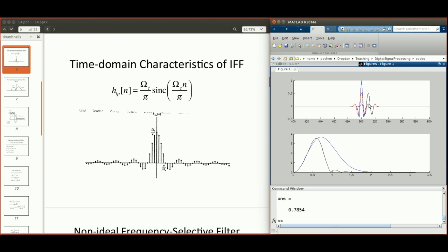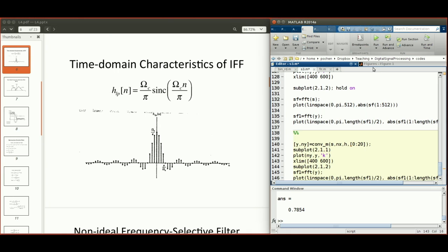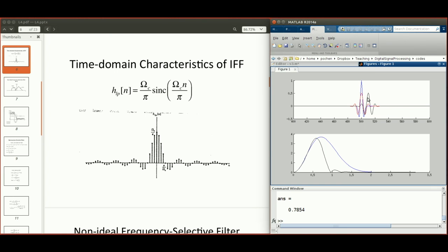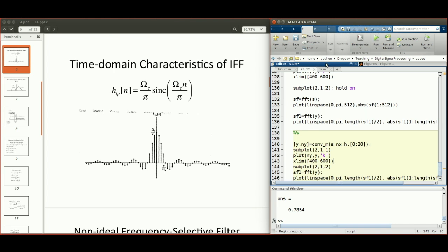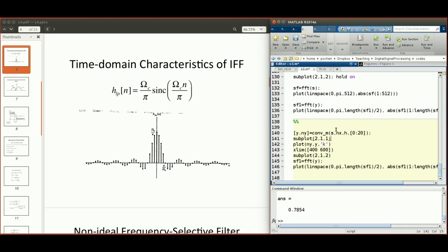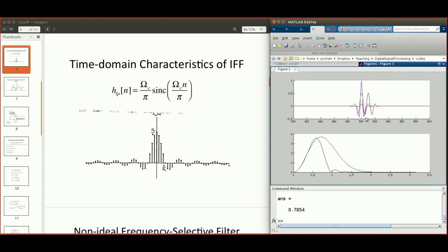But the advantage of this particular shifted filter, the filter that's actually producing the shift, is that it's causal. To compute the output signal, you don't need future points. All you need is past points, past history inputs, and then you can compute the output. You can see the shape of the output is the same as the shape of this zero phase output. The black curve and the red curve, the shapes are identical. The only difference is that it has been shifted by a certain constant amount.